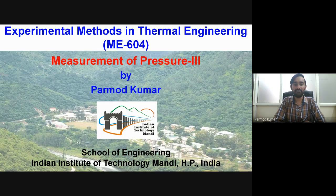In particular, I specified the principle of the strain gauge, and there we mainly discussed the resistance type strain gauge, where the local strain produced in a mechanical component is converted into an electrical signal in terms of its resistance value. Then we started discussion on the measurement of that resistance, and for this we employed the fundamental concept of the Wheatstone bridge for measurement of the unknown resistance.